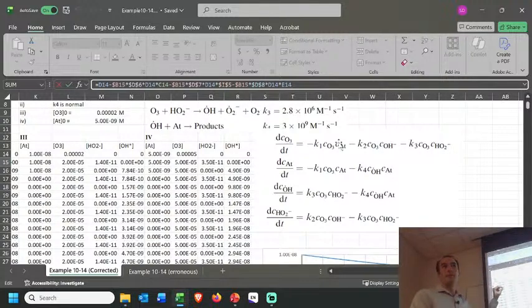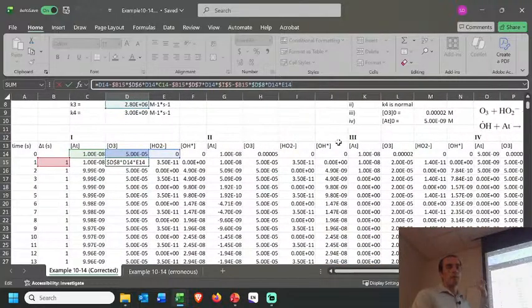So I would take a delta t, which I set to 1 second, so I'm doing 1 second time steps, and during that second, I'm calculating according to what the concentrations were at the prior second. Now, I think there are several different ways of doing this numerical integration, and perhaps taking an average of this one and a guess of the next one might be a better way to do it. I was just taking the previous one and working from there. So there may be some refinement possible, but this should get us very close.